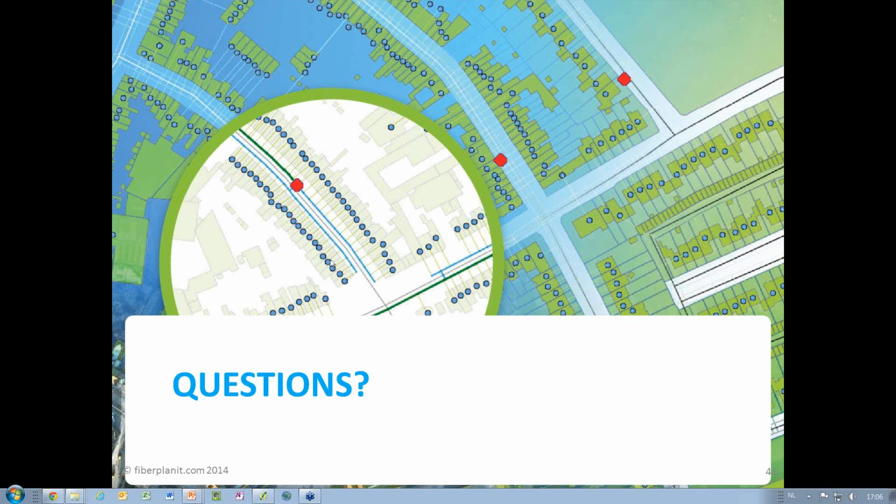Yes, we demonstrated with shapefiles, which is the default format of GIS data that we can always work with. But we also support other formats, such as GML, and even for demand points you can just list them in an Excel or CSV file, as long as you specify the XY coordinates separately.